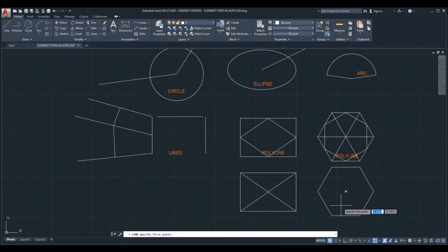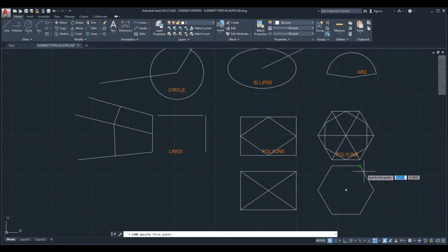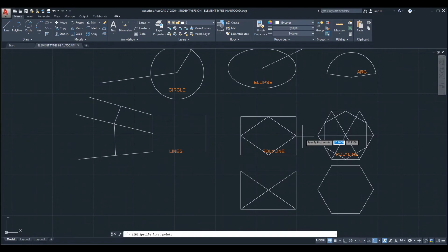Start the line command again. Just by touching the perimeter, we will get this point. By the way, if you zoom in or out, you will lose the center references for either the geometric center or for the circle. Actually, you will lose any references you might see on the snap points.